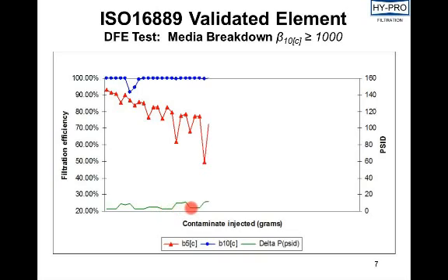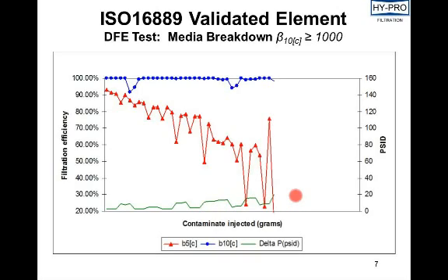As the differential pressure increases and we have changes in flow, we can start to see actually a breakdown in the media, where the filter media may become fatigued, if it's brittle, if it's been damaged in the pleating process, or if it's just not properly supported for a stressful hydraulic system, we can see a breakdown in the efficiency at the rated size.